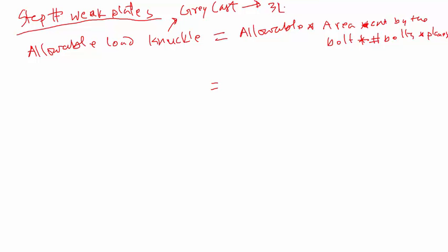That's not in the connection design table. This is from the material properties table. So 32 ksi ultimate strength, and I'm going to use that for this design. That's the maximum cast iron can take shear stress wise.